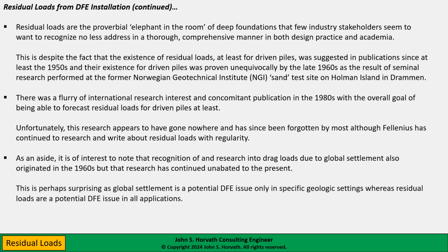I mean, global settlement, yes, it's a potential significant DFE issue, but only in very specific geological settings, typically areas where we have relatively thick deposits of fine-grained soil that are either normally consolidated or very lightly over-consolidated.